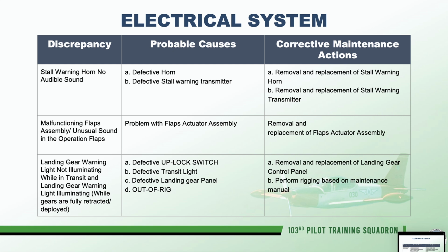Unusual sounds from the flaps assembly often indicate actuator assembly replacement. A worn or damaged flap actuator assembly is a common cause. Remove and replace the assembly to ensure smooth and reliable flap operation.